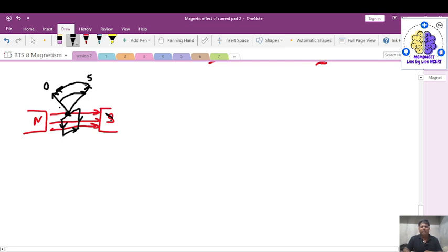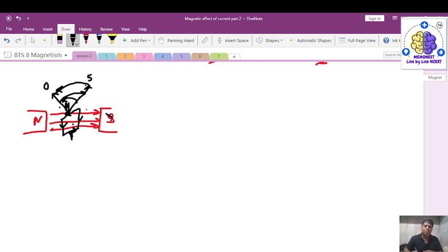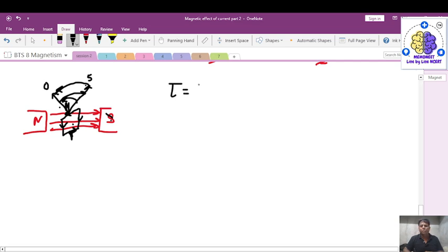So what we do when we pivot this coil in the galvanometer, we fix it with a hair spring. What does this hairspring do? This hairspring helps the coil restore its position once the current has been withdrawn from the coil. Once the current has been withdrawn, this spring will help the coil return to its original position. So if the current is flowing in the coil, the torque experienced by it is equal to N I A B sine theta.